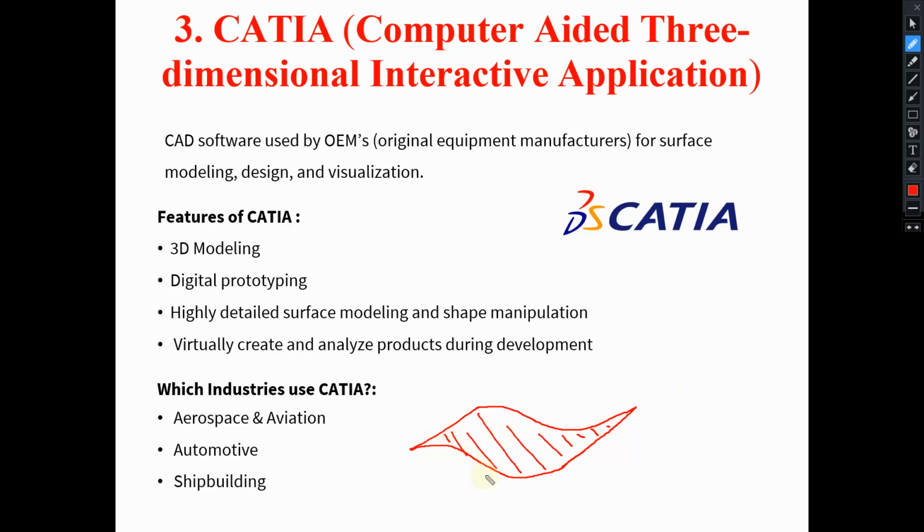So this type of shapes we call as surfaces. So when are surfaces created? Surfaces are created usually when we have to do certain modeling on aerodynamic surfaces, or when we have to create an aerodynamic shape, then we make use of surface modeling. CATIA is very strong in surface modeling, whereas SolidWorks is very strong in solid modeling, where we create a 3-dimensional model.